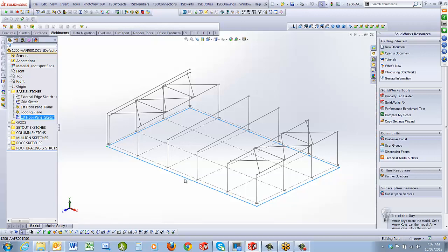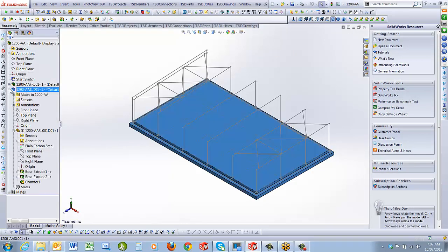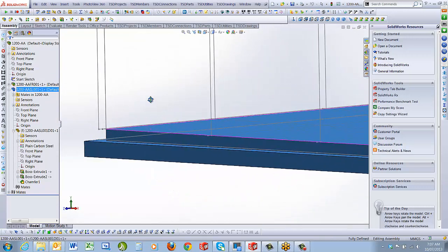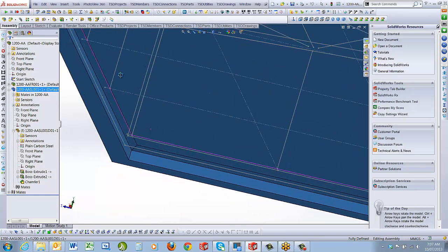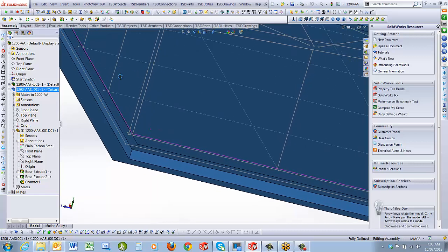Let's just say you don't have a concrete panel going in, you can take out one of these sketch lines and completely avoid that bay. But at the end of the day, I've drawn this line right round in segments to allow me to put my concrete panels on in my driving sketch. Now, also inside my model, I've created a slab, which is simply just a concrete extrusion and a footing around the base, and this will allow us to create dowel plans down the track for the dowels that have to go in. Now, predominantly I'm going to talk about tilt panels.